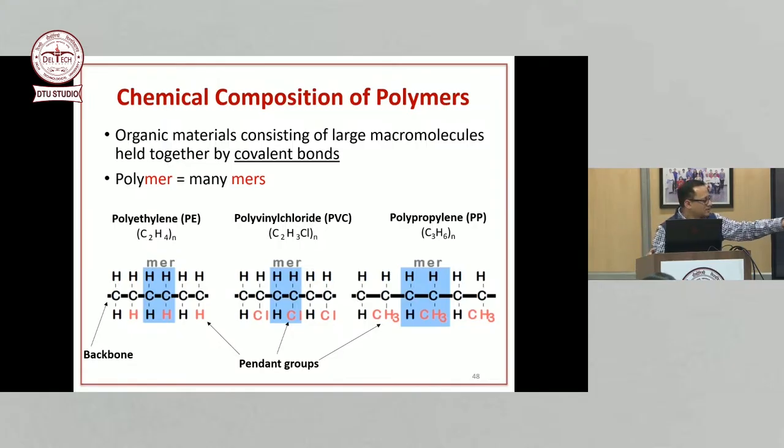This is like a backbone of polymer. So carbon, carbon, carbon, these are the backbone. And now you can have pendant groups. If you change the pendant group, you're just making a new polymer. So in polyethylene, you change that hydrogen to chlorine and now you have PVC. A very different polymer, very different properties. You can use it for different types of applications. You change it with a methyl group and you have polypropylene, and now it's a very different polymer. So for polymer chemists, this is easy stuff, they can easily play with the properties of a polymer and change the properties of the material.